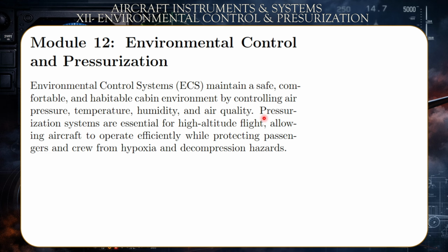Okay, so pressurization systems are necessary and essential for high altitude flight, allowing aircraft to operate efficiently while protecting passengers and crew from hypoxia, which is the lack of oxygen, and decompression hazards, in which a low pressure would cause a high pressure of your own body. The blood within your own body would try to escape. It would start pushing outwardly against your skin. Why? Due to the low pressure.